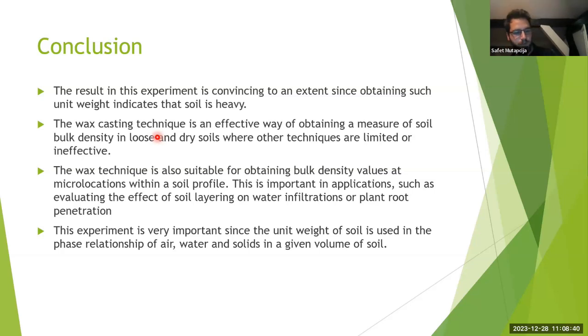That usually happens with earthquakes because, with an earthquake, the grain distribution with the water changes. It's not taking hours. It can take just 3 minutes of earthquake for your soil layer to lose its bearing capacity, and that's enough for the sinkhole to form or start forming.